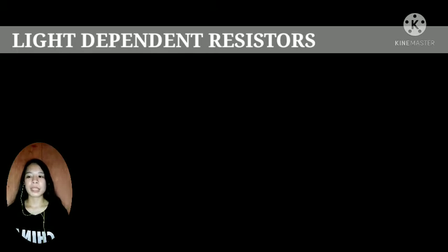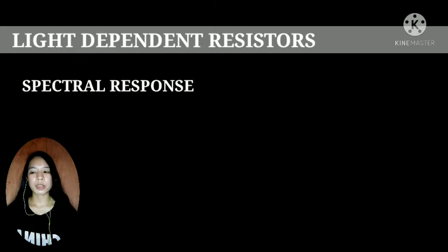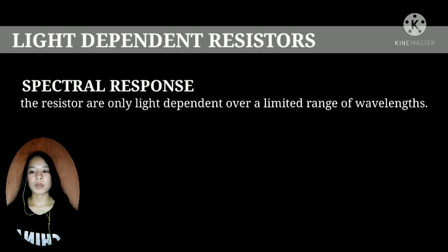Practical light-dependent resistors are available in a variety of sizes and package styles, and the most popular size has a face diameter of roughly 10 mm. So let us proceed to spectral response. The resistors are only light dependent over a limited range of wavelengths. Light-dependent resistors have their maximum response at about 680 nanometers.